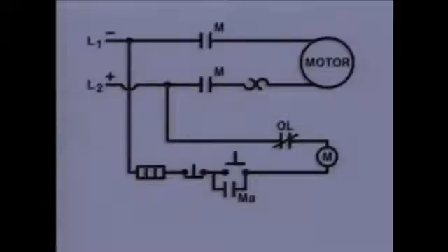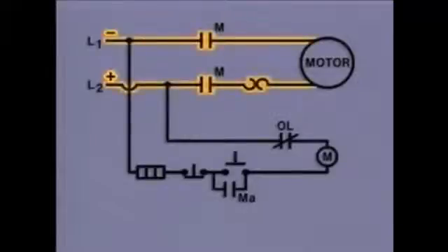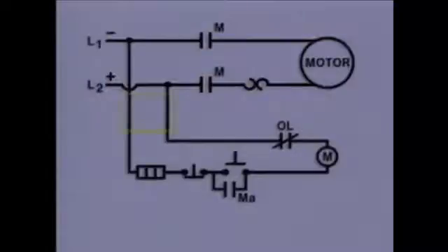Generally speaking, DC motor controllers differ from AC motor controllers in that DC motor controllers use direct current instead of three-phase alternating current. There are only 2 lines in the power circuit of a DC motor controller instead of the 3 lines in an AC motor controller. And DC motor controllers do not use a step-down transformer. The control circuit of a DC motor controller operates using the same level of voltage that powers the motor.